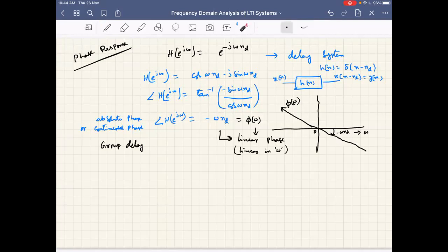One easy and clear property you can see is, if there is a linear phase in the system, it only introduces a delay in the signal, no other modification to the input signal. That's a very desirable characteristic. In some cases, we don't want to modify the signal. At the maximum, we could allow only the delay because of the filter that we design or because of any system that we introduce. We don't want to change the phase response. We only want to modify the magnitude response.